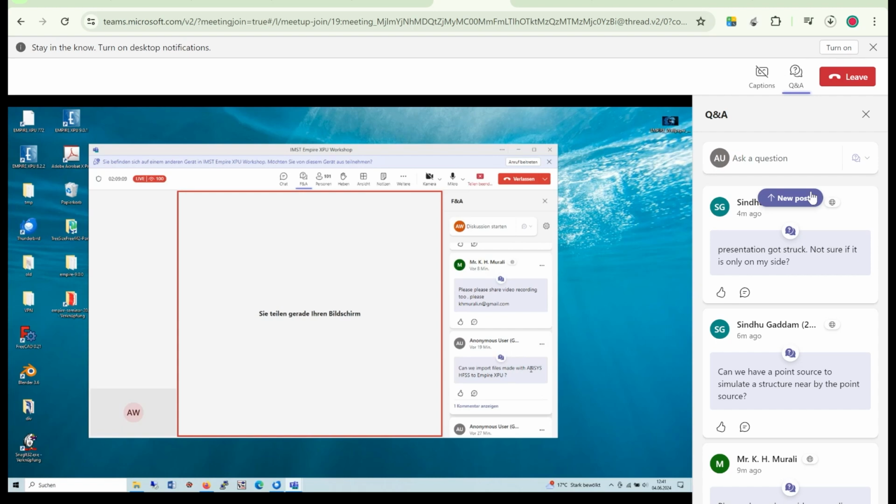That means all the geometry and materials will be assigned, but at least the ports have to be added. So the ports we can usually not import because we have other port methods available. But the geometry and materials can be imported from other software.